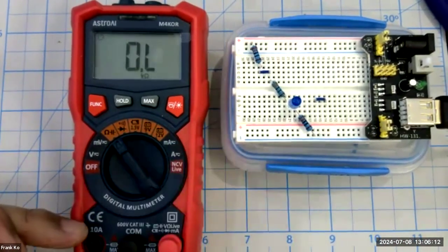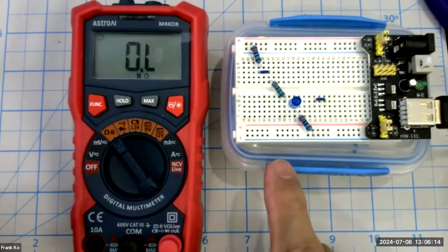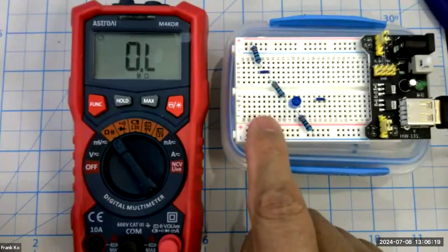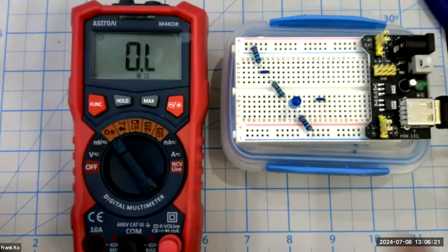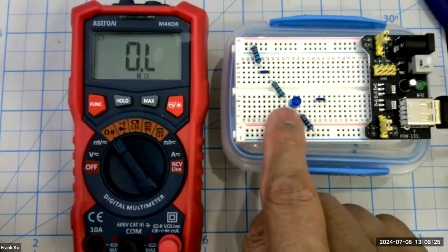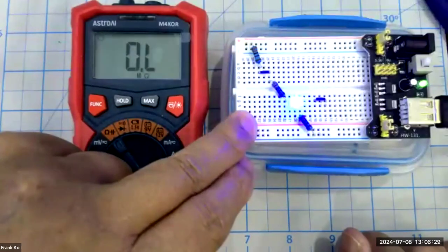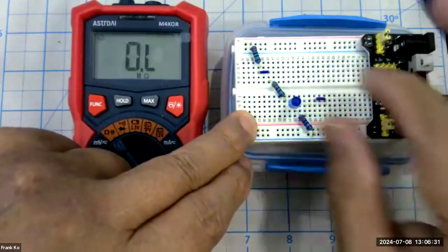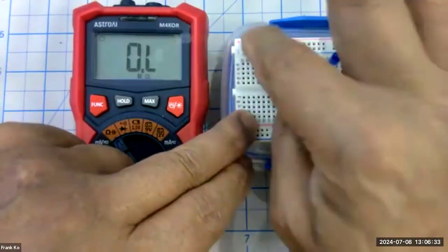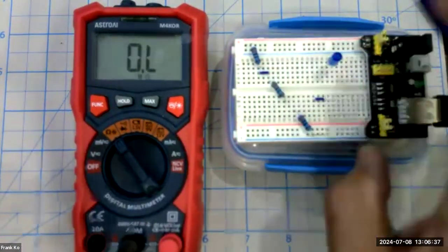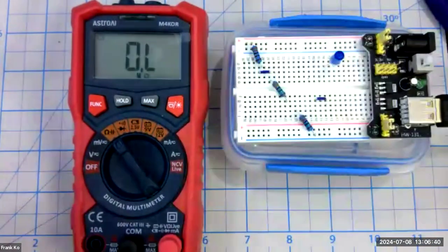Next, you want to double check the resistance measurements. And as I've said before, you cannot measure the resistances on the board if there's any connection to the power supply. So I can remove the connection to the power supply by breaking the circuit open at the LED. The LED is there only to show us, yes, we have a complete circuit. Pull that out. And then now we don't have any solid connection between all 3 resistors to the board. I can measure each one of these separately.